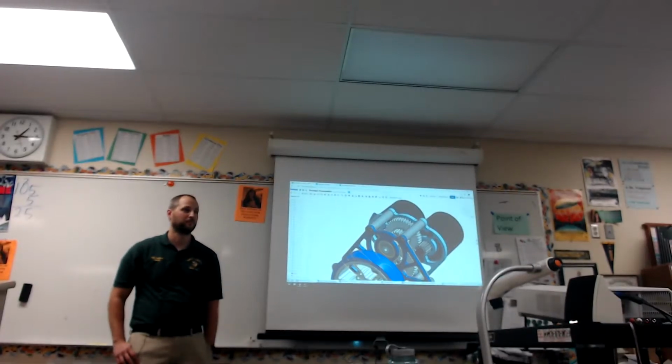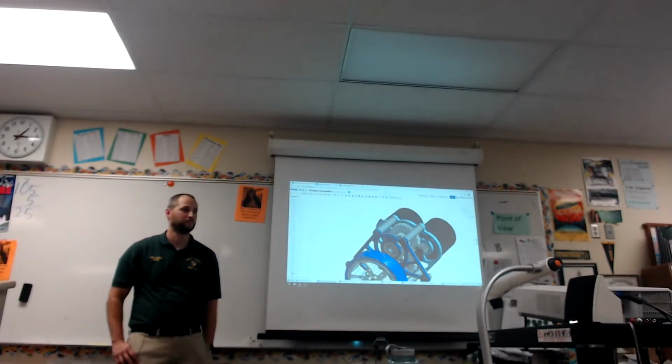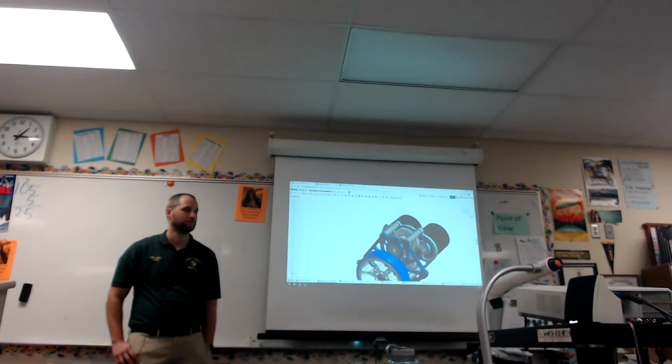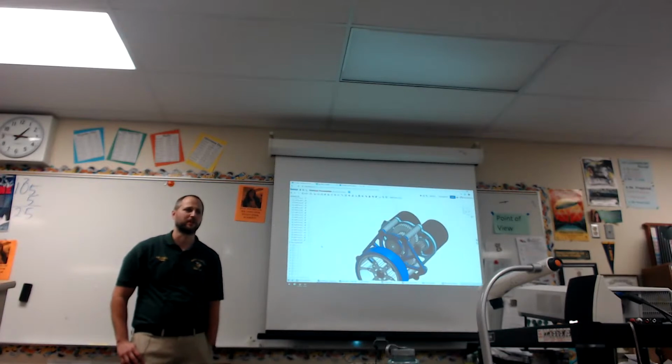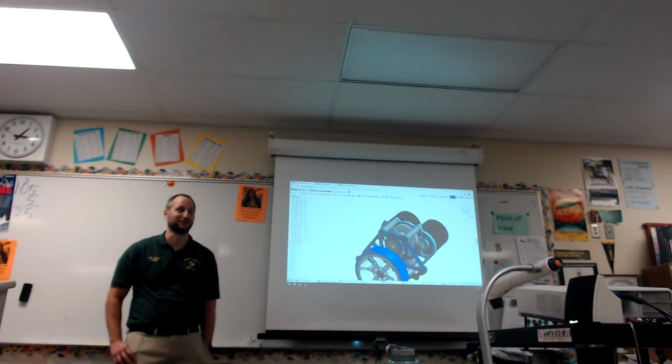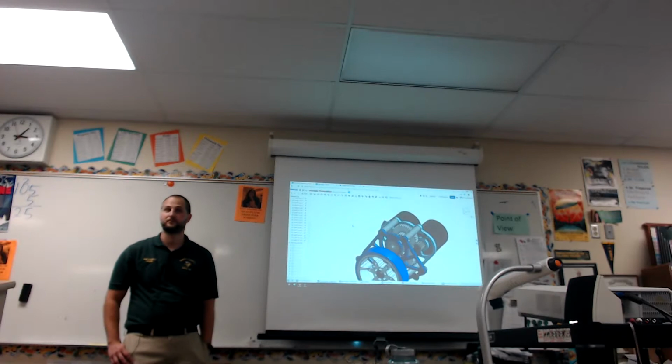And can you use variables to eliminate the step where you have to manually type in the gear ratio? I don't know if you can use variables on assemblies. I'm pretty sure the variables are only on Part Studios. That's not something we've come up against yet, so I'm not sure. Yeah, sorry. Wish I had an answer for you. I mean, I can check variables. No, not on assemblies. It's only on your Part Studios.